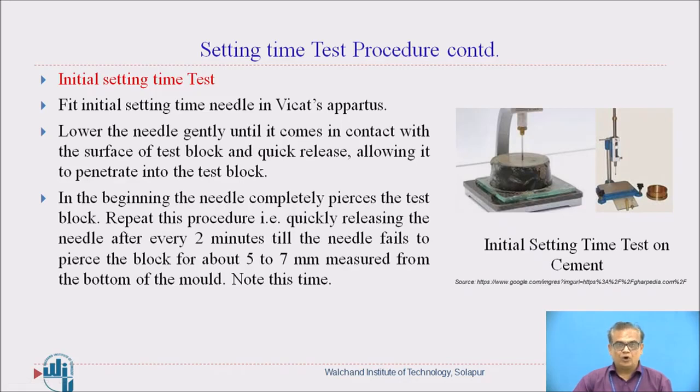That particular time is recorded, and the time from addition of water to cement to this particular moment is reported as the initial setting time of that particular cement, right? And this initial setting time should not be less than 30 minutes. Remember, the minimum setting time of cement should be 30 minutes, right?